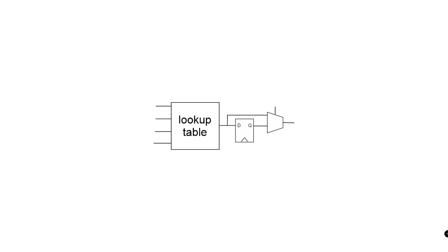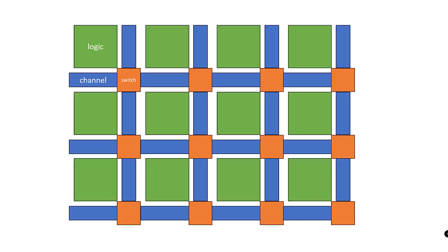The Field Programmable Gate Array, or FPGA, is an important platform for building logic gates. One common type of FPGA uses a memory as a lookup table to implement a truth table in circuitry. Many of these also include a register to store a value. Field Programmable Gate Arrays have a number of these programmable logic cells. They also have programmable interconnect to connect together the various gates to create complex logic circuits.